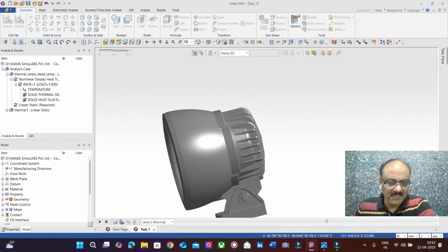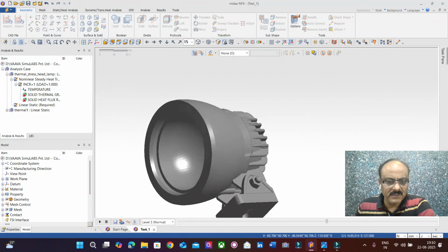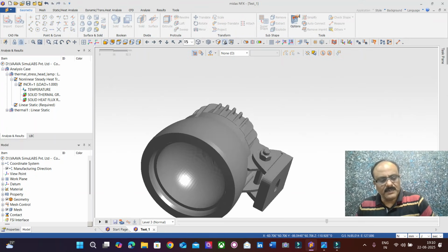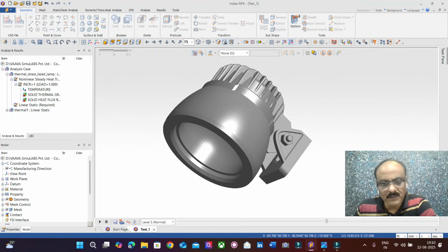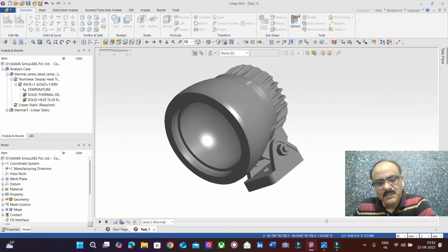And now from the 3D model we are going to carefully mesh it with the meshing processes. Okay, now since it's a 3D model, there is a certain process in which you can convert the elements. We can split every model. This particular model can be broken into about 10 parts or 15 parts or 20 parts, depending upon the requirements, and each part can be individually meshed.